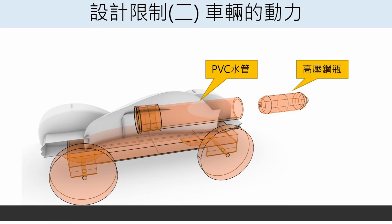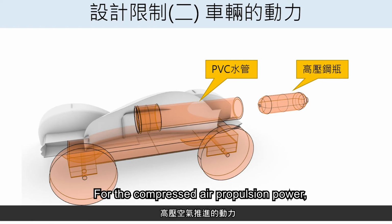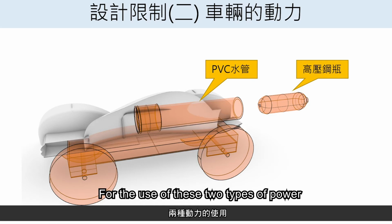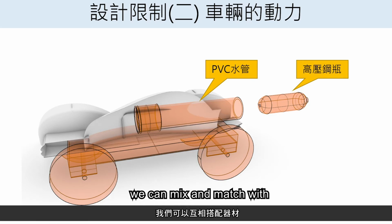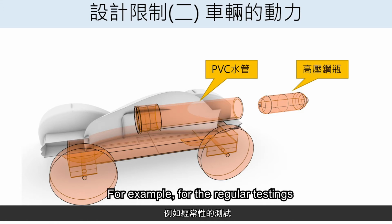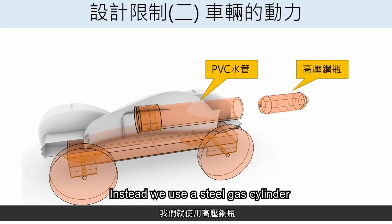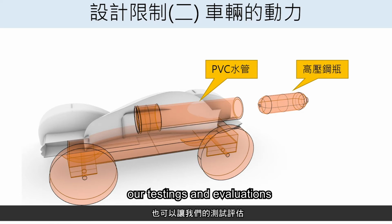I hope you can have a wider range for design production. Design restriction 2. Vehicle power. For the compressed air propulsion power, a PVC tube of 18 mm inner diameter can be used, or 6 and 12 cubic centimeter steel gas cylinders. For the use of these two types of power, we can mix and match with different equipment and resources. For example, for regular testing, maybe we use a self-made PVC tube propulsion system, and for final testing or racing competitions, we use a steel gas cylinder. Not only can we save resources, our testing and evaluations can be more comprehensive.